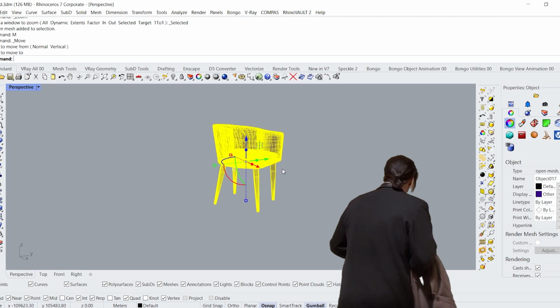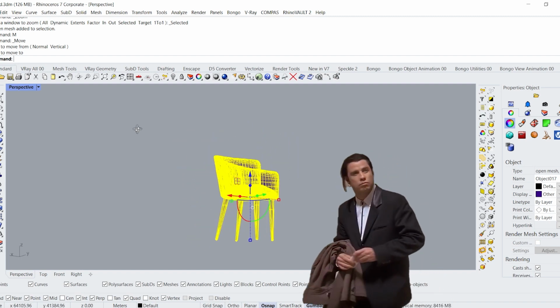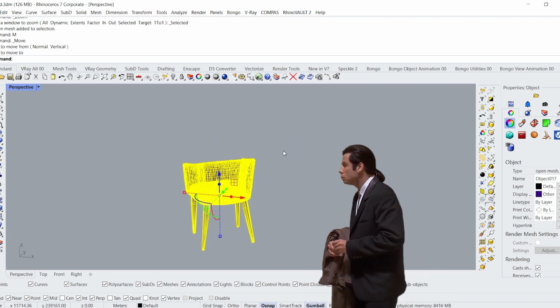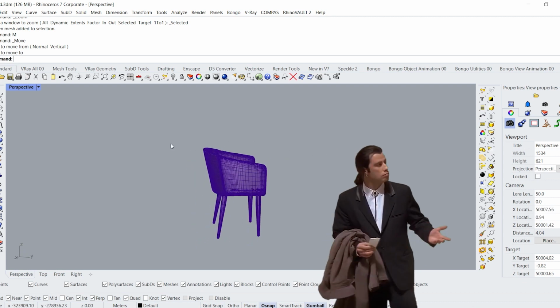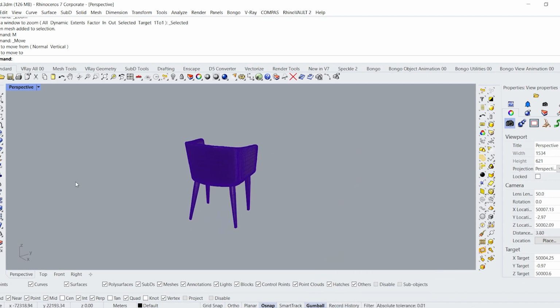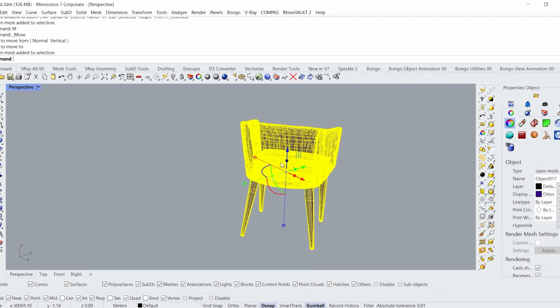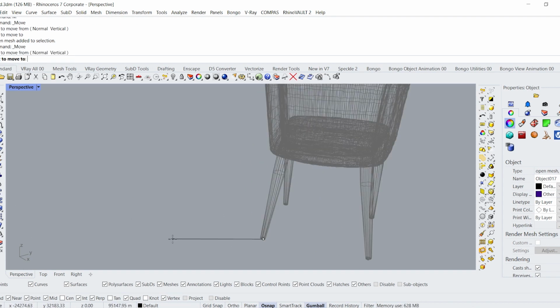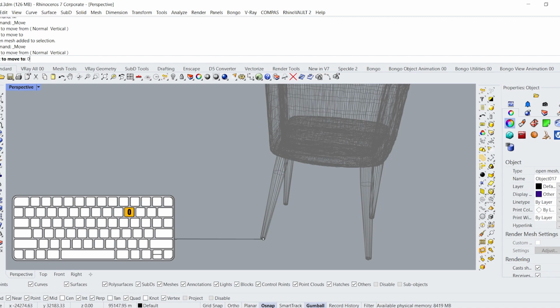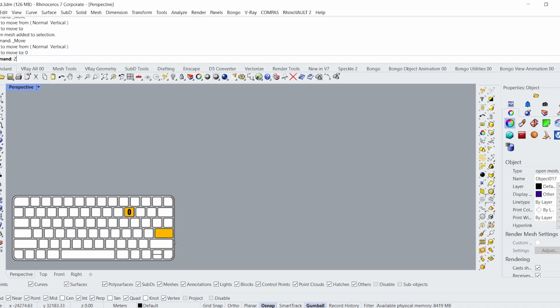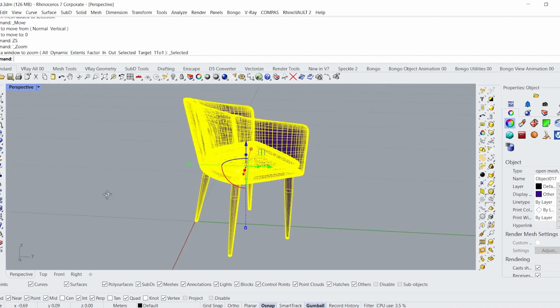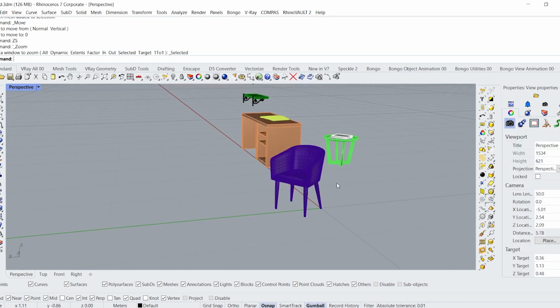Number 2. Zero Enter. Ever had those "where am I" moments while working? Yep, we've all been there. The best way is to move the object to the center of the grid. With the Move command, get a snap of an object. Type 0 and press Enter. Boom! You've got a one-stop center point.